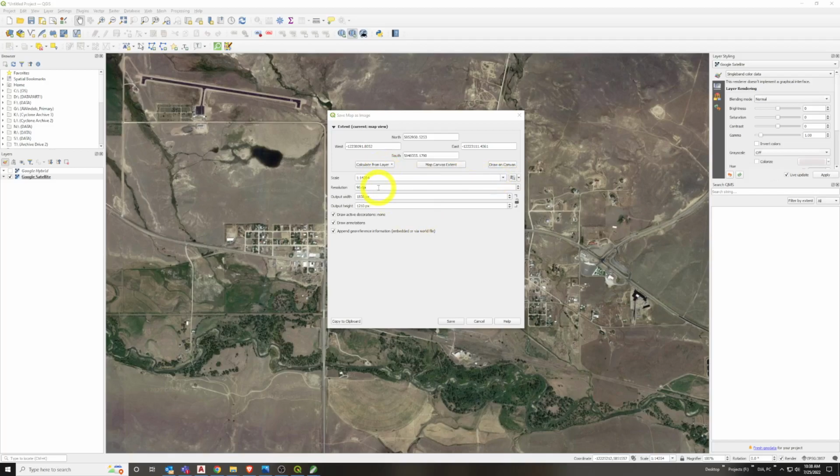Now, the second layer of control, or major level of control, is how much resolution on the aerial. And this can be tested out. 96 dpi, dots per inch, is generally for your computer screen, but from what me and some of my colleagues have been finding out is we'll do it at 1,000, and this controls how zoomed in and how much resolution the aerial is going to have. We've gone up to 2,500 plus before. This is the controlling factor on the size of the file. You can see the pixels go way up. So let's do 2,000 here, hit enter.